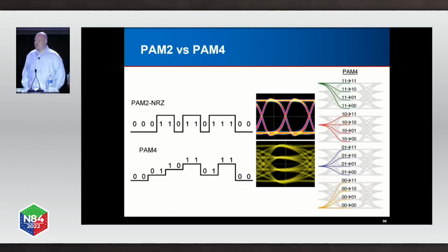Another thing, I said there's other ways that we can increase the density. What you can do if you stay in amplitude modulation is go from NRZ, which is another way to describe it, PAM2. It's pulse amplitude modulation, and there's two states. So right, 1 and 0.